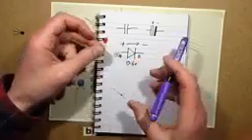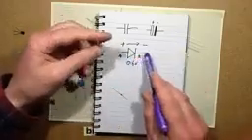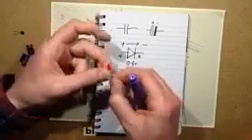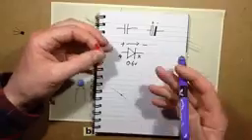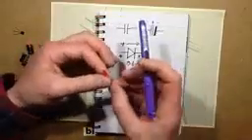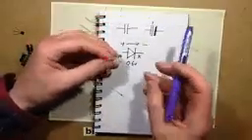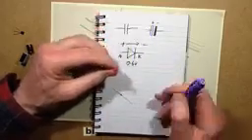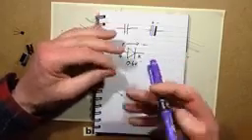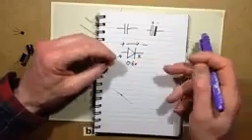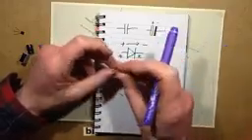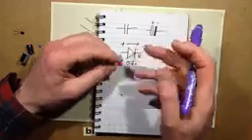But one of the things you have to note with an LED is, because they're optimized for emitting light, they don't have a high reverse blocking voltage. It's usually just about 5 volts. So if you were to connect the polarity wrong and exceed about 5 volts, then in the case of white, blue, green LEDs, it may damage them, but with red ones, they may end up just conducting in the wrong direction, but not lighting, and not suffer damage.